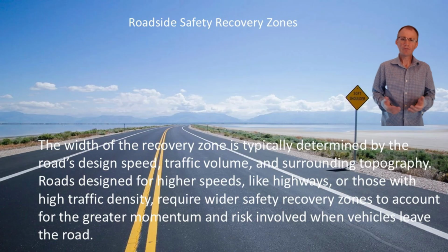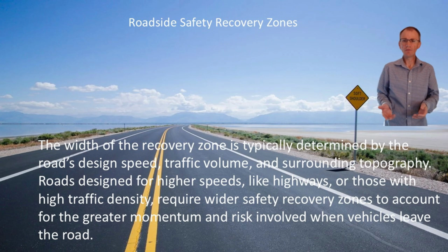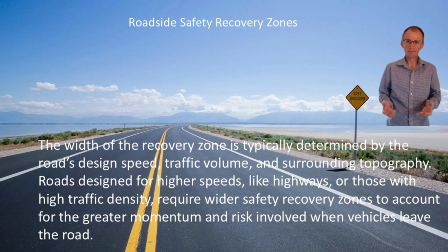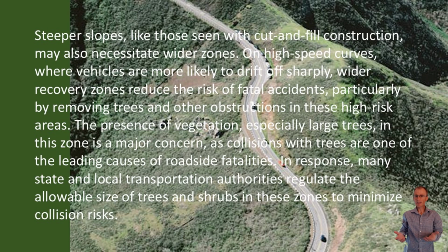Roadside safety recovery zones. The width of the recovery zone is typically determined by the road's design speed, traffic volume, and surrounding topography. Roads designed for higher speeds, like highways or those with high traffic density, require wider safety recovery zones to account for the greater momentum and risk involved when vehicles leave the road. Steeper slopes, like those seen with cut-and-fill construction, may also necessitate wider zones.